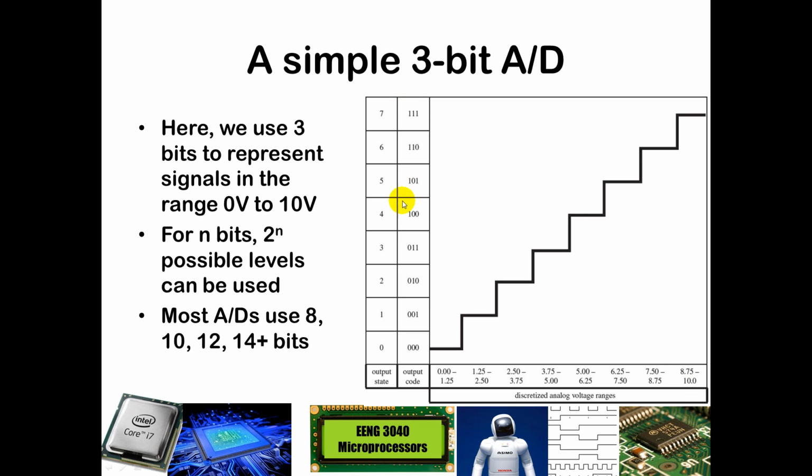You can think about the most significant bit as effectively determining whether you're in a higher voltage or a lower voltage situation. So if you are greater than halfway, that is greater than this 5.0 right here, then your most significant bit is set. If you go on and split into two halves there, then you can once again subdivide, and amongst that upper half, if you have a 1, then you are in the upper quarter, the top eighth and the next eighth. If you have a 0 there, then you're in the next quarter, and that puts you somewhere here.